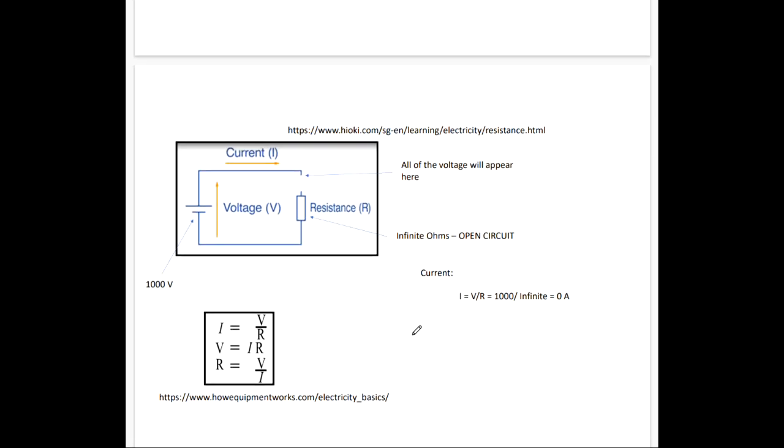In opposite kind, let's look at an open circuit. Well, in an open circuit, current can't flow. So if current can't flow, we have the voltage of the source. There's no current. So all of that voltage will appear right here. It's just like measuring the voltage here. It's going to be the same here, and even right there. Even right here. And no current's going to flow.